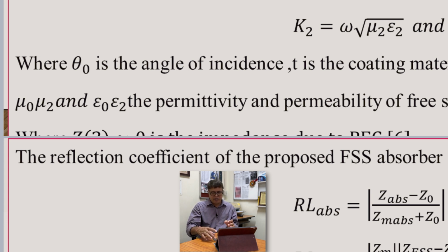Of course, we have designed an absorber at 2.4 gigahertz as well as at 1.6 gigahertz, where you will see that these are the three SRRs which correspond to 2.4 gigahertz, where the microstrip line length is L and in between there is a gap. This gap corresponds to the capacitance formed. So the total structure of each ring will have a particular value of C and a particular value of L. So these three are coupled to each other.